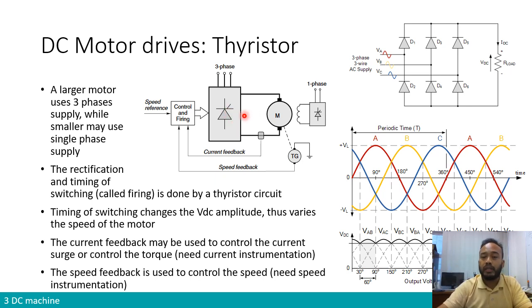There needs to be a command at the gate. The symbol of a thyristor resembles a diode, because it is a semiconductor that lets current go through in a certain direction, but we have this extra terminal, the gate, where we deliver the control. We can tell the thyristor when to operate, when to allow current to circulate.